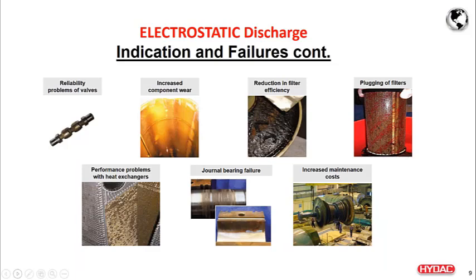Plugging of the filter because of the varnish and the contaminants. Then performance issues in the heat exchangers because of the micropitting, and also the discoloration of the heat exchanger. Journal bearing failures because, again, same thing, micropitting events, and also the increased maintenance costs. So all of that are indications of the electrostatic charging.